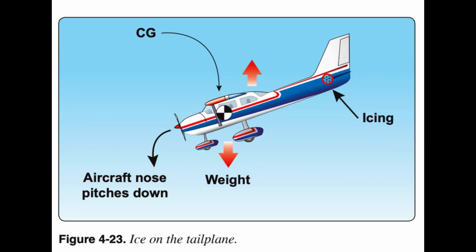If any of the above symptoms occur, the pilot should: 7. Immediately retract the flaps to the previous setting and apply appropriate nose-up elevator pressure. 8. Increase airspeed appropriately for the reduced flap extension setting. 9. Apply sufficient power for aircraft configuration and conditions. High engine power settings may adversely impact response to tailplane stall conditions at high airspeed in some aircraft designs. Observe the manufacturer's recommendations regarding power settings. 10. Make nose-down pitch changes slowly, even in gusting conditions, if circumstances allow.